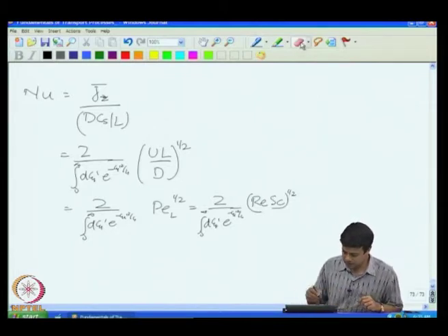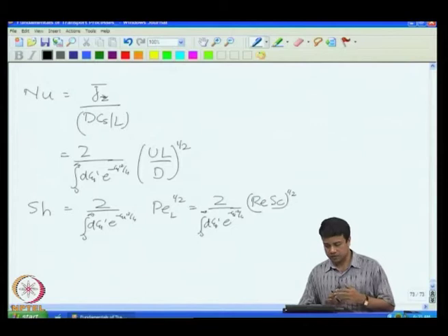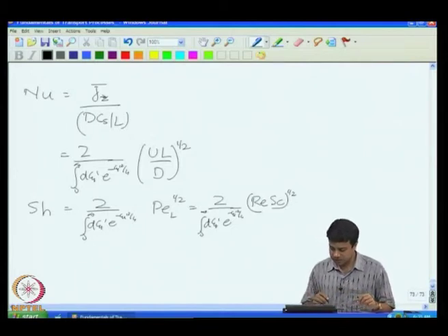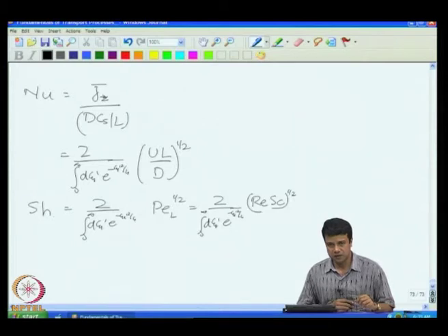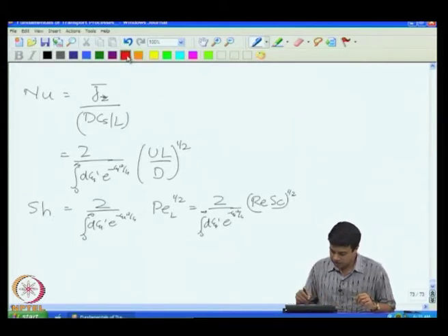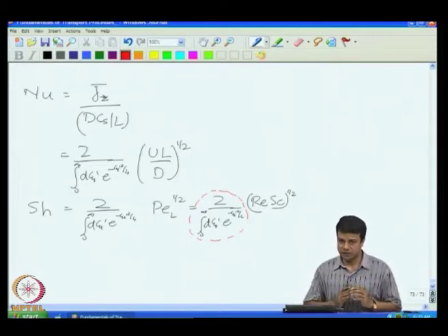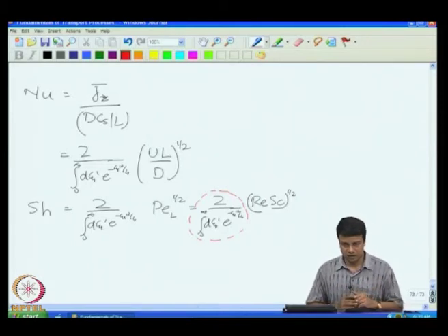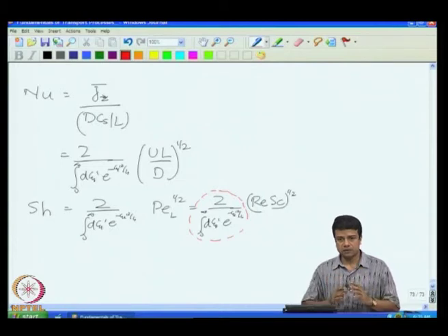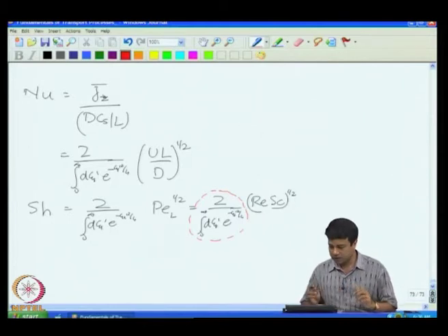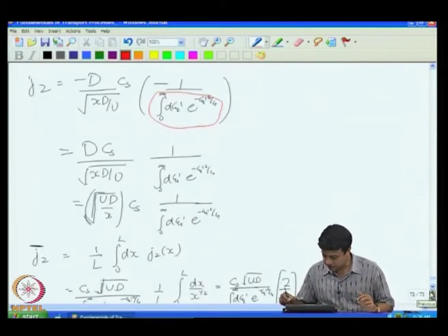For mass transfer, this is also often called the Sherwood number. The Nusselt number for mass transfer is called the Sherwood number. This gives me the correlation between the Sherwood number, the Reynolds number and the Schmidt number. And what is sitting in front is a constant, which we had determined explicitly by considering the entire field for the concentration in this thin film. We did not just do dimensional analysis for an average concentration difference as a function of an average flux. We actually did solve the problem using shell balances subject to certain assumptions, and got the variation of the entire concentration field within this thin film.